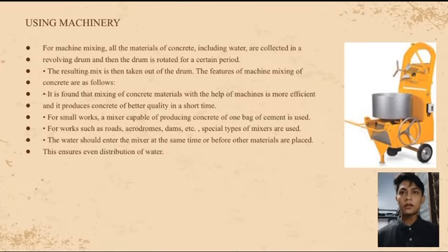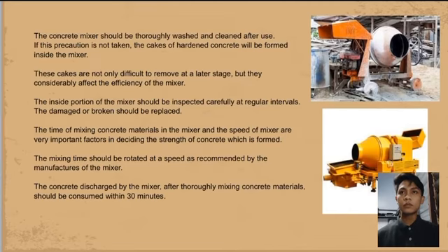The water should enter the mixer at the same time or before all other materials are placed. This ensures even distribution of water. The concrete mixer should be thoroughly washed and cleaned after use. If this precaution is not taken, cakes of hardened concrete will form inside the mixer. These cakes are not only difficult to remove at a later stage, but they considerably affect the efficiency of the mixer. The inside portion of the mixer should be inspected carefully at regular intervals. The damaged or broken parts should be replaced.